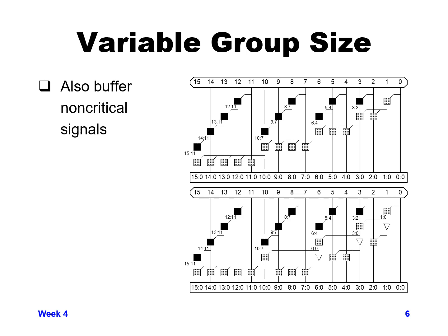Unfortunately, we can't play that trick on the last stage because bits 11, 12, 13, 14, and 15 are all happening in parallel at the same time. So no one of them is necessarily slower or the most critical one. They're probably all critical at that point. So the last stage that has the most capacitance, we can't really do anything about because we need all 5 stages to receive the carry coming in at the same time.